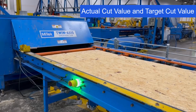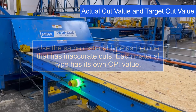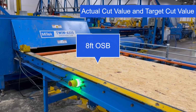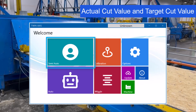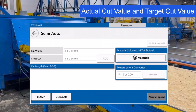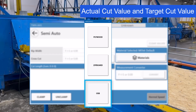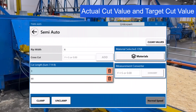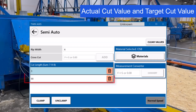To find the target cut value, start by using the same material you calibrated with and noticed inaccurate cuts on. For this example, we will use an 8-foot sheet of OSB. Load the board onto the in-feed. From the home screen, select the Semi-Auto button. For our example, we will select OSB as the material type, then configure a cut with a 6-inch rip width, 3-inch crosscut, and a 90-inch crosscut.